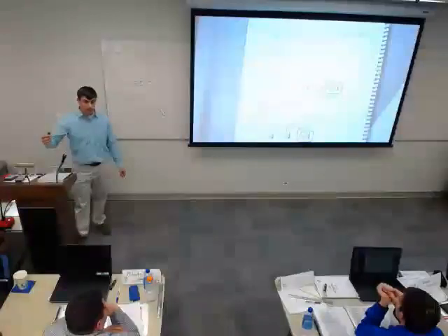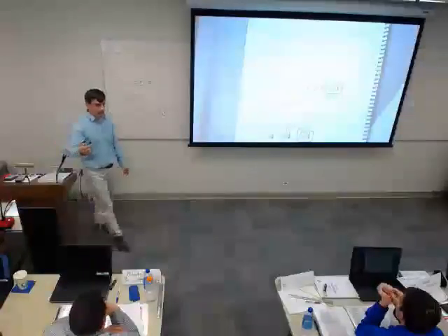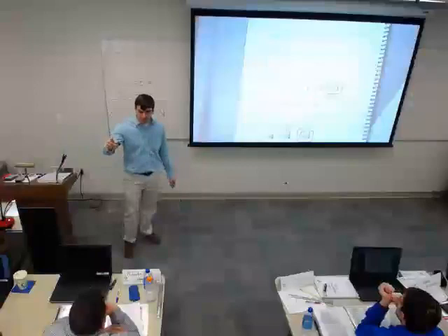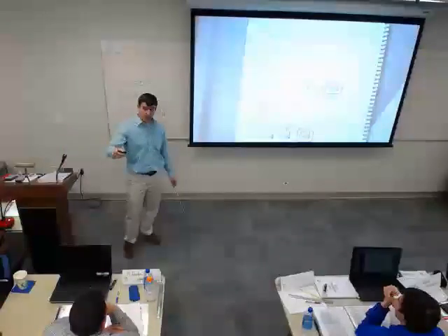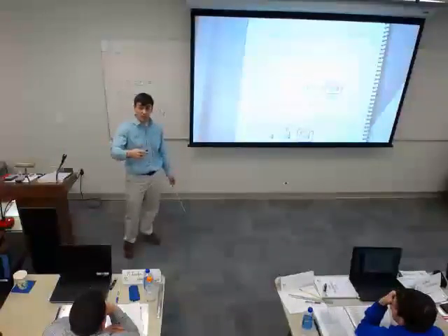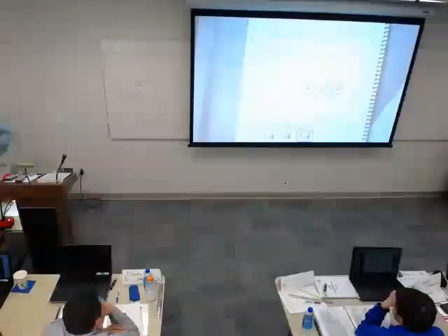And what am I going to do with my velocity pressure? What do I do with that number? Yes, I'm ultimately going to get my CFM, but I'm going to use that to get my velocity, which was 4,005 times the square root.